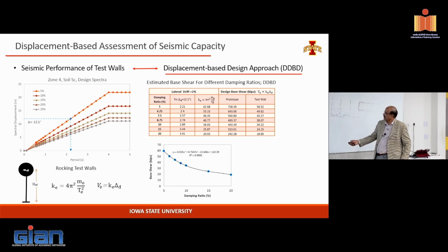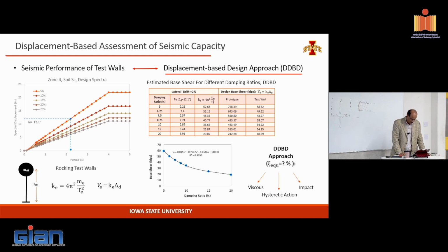By doing this manipulation, you can actually control both walls without causing any large drift, for example, what we've seen. So that's what this is all about. As the damping goes down, maybe you increase the design force slightly, and you will improve the performance of the structure. That was the idea.